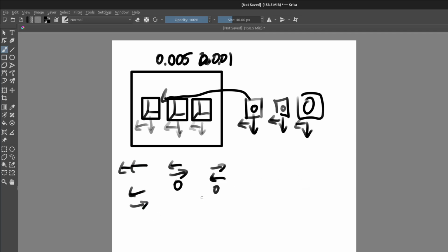And this is really only applicable when you start getting to a very large number of cavities in a mold. So when you've got 16 different cavities, the chances of having one of these line up so that it just happens to cancel out the tolerances of manufacturing starts to become extremely likely.